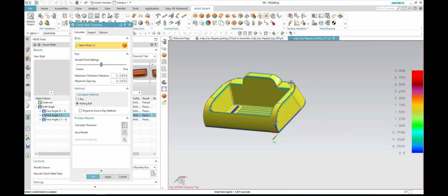You get some sort of warping distortion. Some area might sink. You get defects basically. If you have thin walls, on the other hand, you will have a weaker structure. You might have a poor surface finish. You might have ejection difficulty as well. So you have to balance it. This is what this stage is revealing for us.